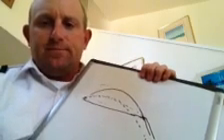We're going to talk about ailerons and their effectiveness in controlling an aircraft and changing its flight path. An aileron is simply a control surface that's hinged to the trailing edge of a wing, and it's actuated by the pilot through the yoke and then through a series of cables and pulleys, levers and rods, or a hydraulic system. When the pilot, for instance, turns the yoke to the left, the left aileron is raised into the relative wind, and the right aileron is lowered into the relative wind. What this does is change the camber and the mean chord line of each of the airfoils.